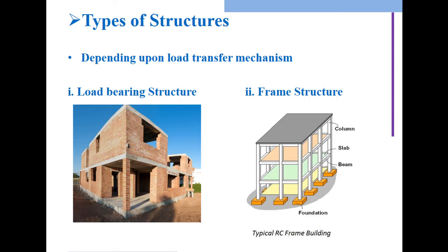So whenever you are going to assign any kind of loading, you need to assign the self weight to the overall structure. But before assigning the load, you should confirm that your structure particularly consists of each and every type of material or element which you have to design during the overall analysis. Then and only then the self load will be considered.